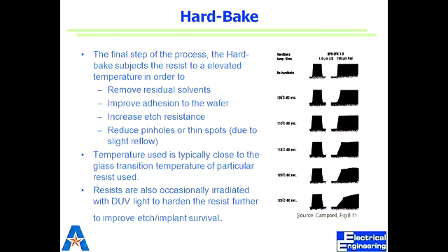Any film we deposit or grow, however we get it on the surface, if it has mechanical defects where we have very small cracks or openings, we call them pinholes. Pinholes are small, round-shaped defects which may go all the way or may not go all the way. But when you do harsh treatment, they're going to become big and go all the way. So they're going to result in a defect at that place where the resist was supposed to cover everything.